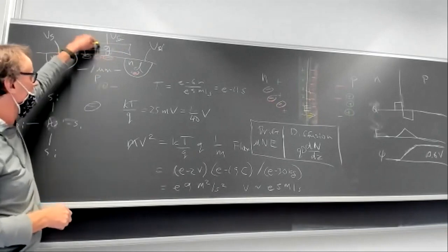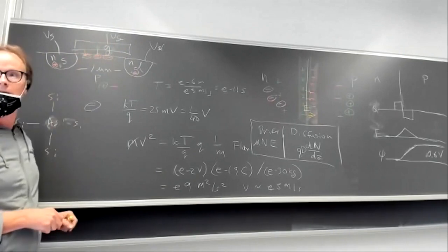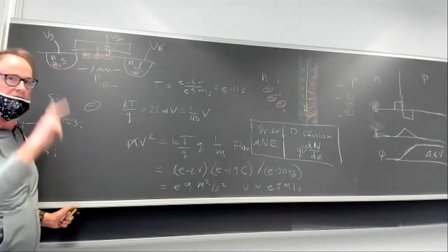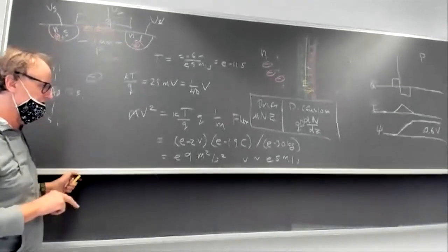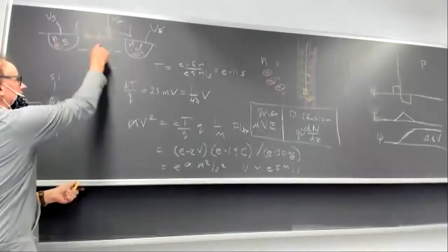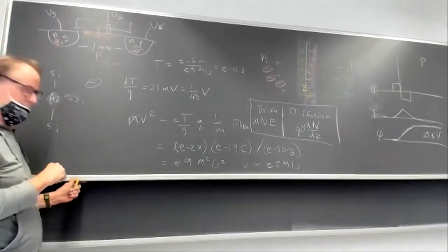So every charge you put on the gate is balanced by a mobile electron that came from the source. And that's the region I'm talking about here. It's not a vapor of electrons, it's really a sheet of charge, a macroscopic sheet of charge, which has a higher density than this doping density. That's kind of the threshold amount.